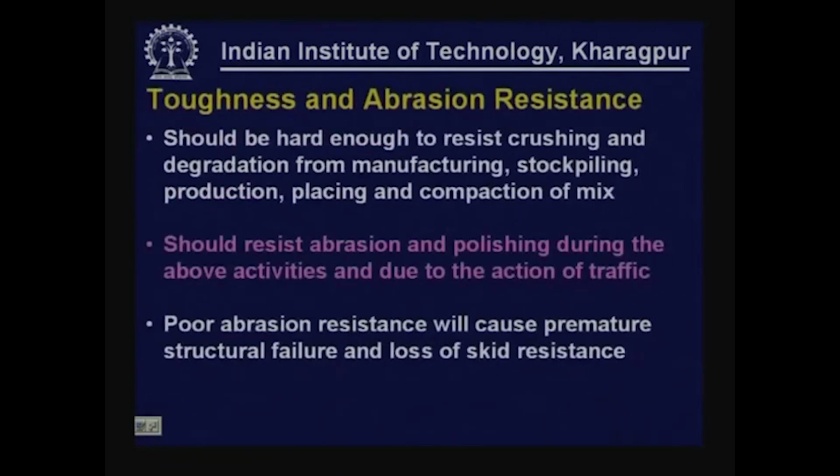The toughness and abrasion resistance of aggregates: the aggregate should be hard enough to resist crushing and degradation from manufacturing, stockpiling, production, placing and compaction. The aggregates undergo various operations before they are finally used. In all these operations the aggregate should not get degraded, and should not get crushed before all these operations are complete,